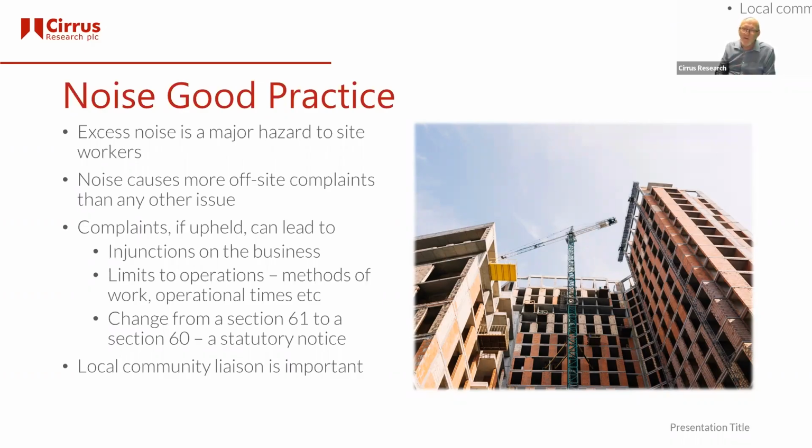It can limit the operations of the site, either just the methods of work, the operational times, these sort of things. It can have a major impact on the schedule of a construction project. And as I said right at the beginning, if it's serious enough, it could switch from an agreed Section 61, where everybody's happy with what that particular site is doing, to a statutory notice Section 60, which may, again, severely limit what's happening on the site.